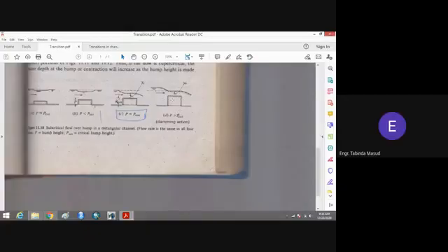However, this will be an uneconomical case, because it will be a costly project for you to have the height of the hump greater than this height of the hump. So it's better to have this height of the hump. If you want to have a critical flow over here, this will be an economical control section, and if you increase the height of the hump, it will get uneconomical.